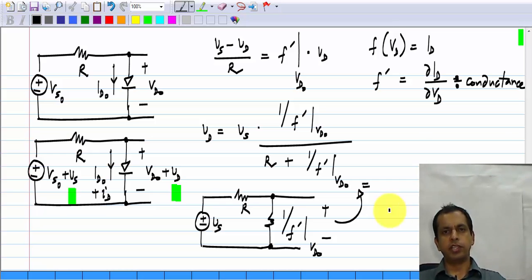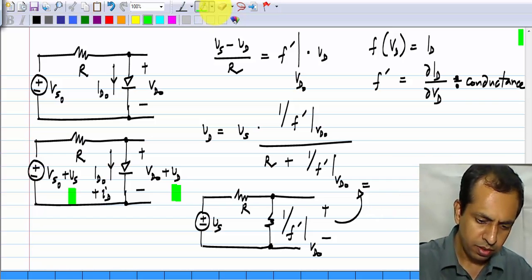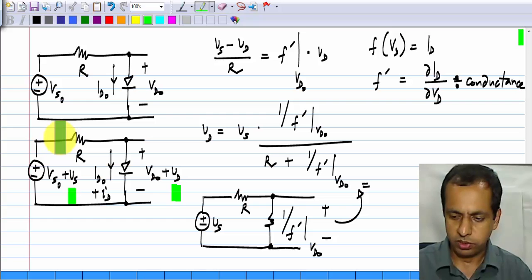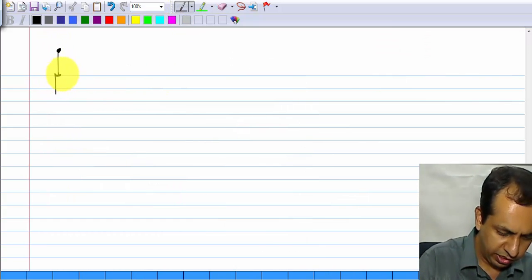So, the reason I showed the equations is to show that it is a general method. Now, what I will show is that every nonlinear element can be replaced by a linear equivalent, and the resulting equations will of course be the same as what you would get if you expanded every nonlinearity in a Taylor series and neglected higher order terms. So, instead of considering the whole circuit, what we can do is to just consider a single element.